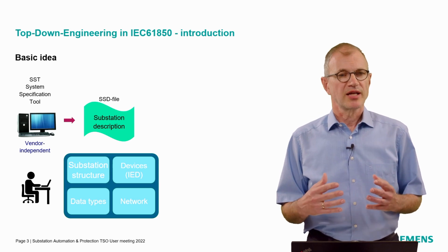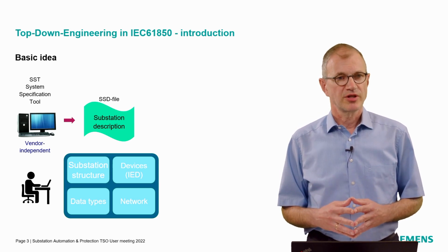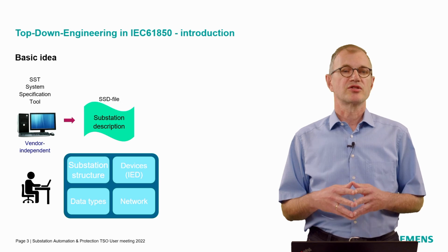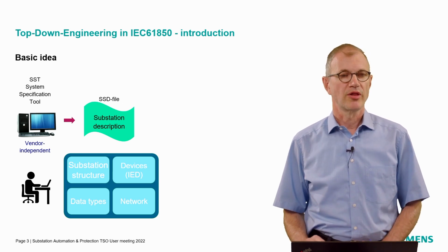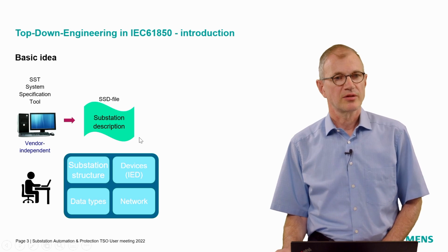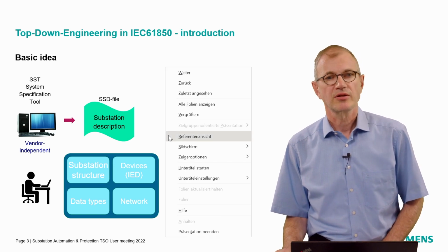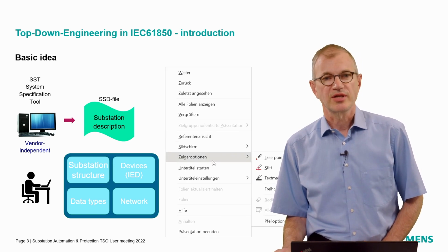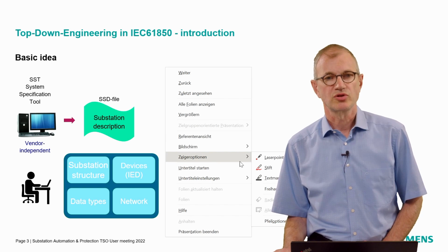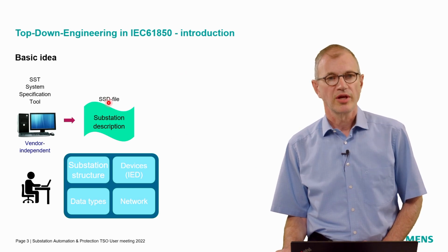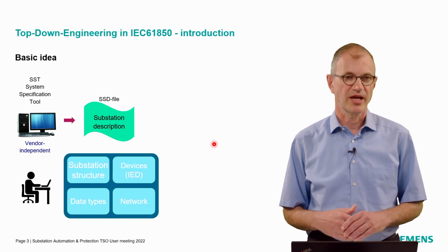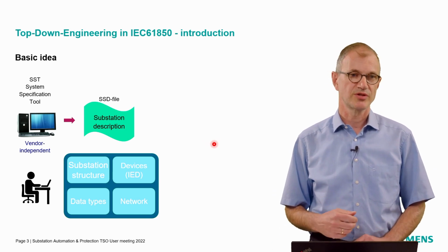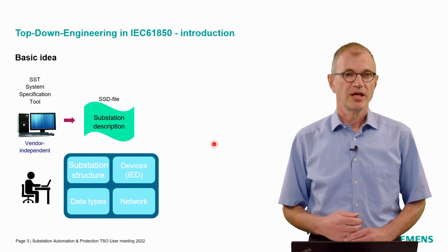The idea of the 61850-6 is that there is a system specification tool, you can see it here on the left side, and that you can create with that a substation description, the SSD file, which is described in this SCL language. This is XML based. We will see an example later.